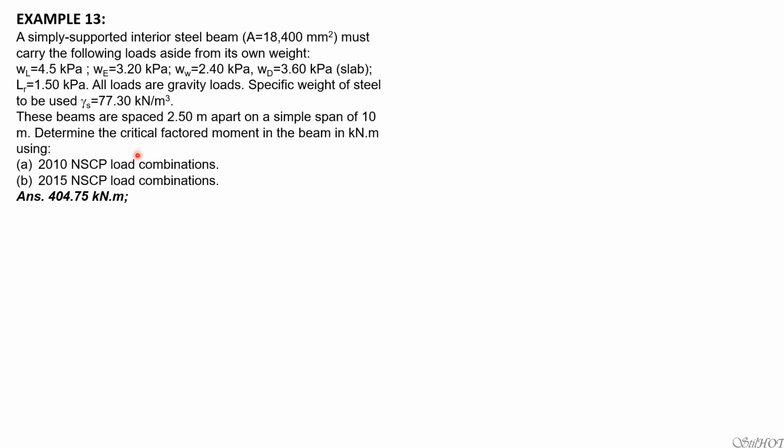These beams are spaced 2.5 meters apart on a simple span of 10 meters. Determine the critical factored moment in the beam in kilonewton meter. The critical factored moment is the maximum moment based on the load combinations given.